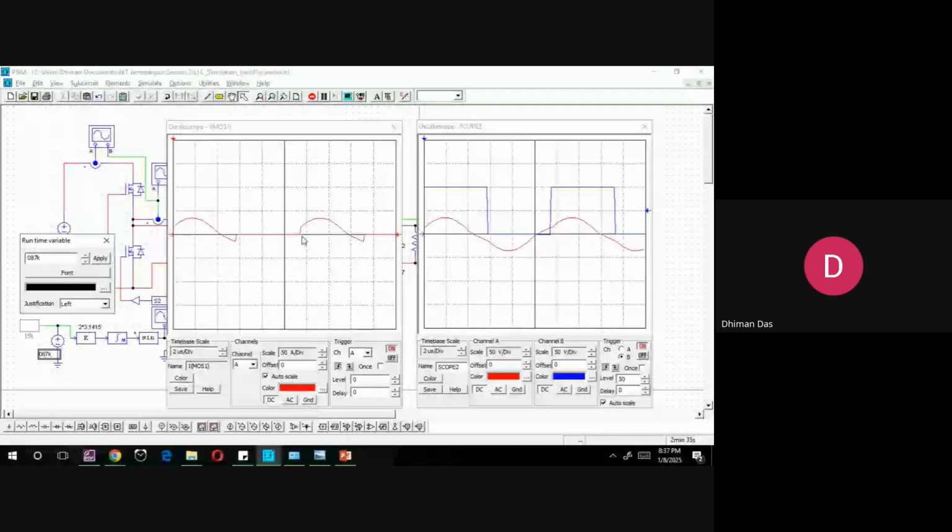That means here it happens ZCS and it goes into the capacitive region of the gain curve. So here this is ZCS, negative current at turn off, but I need negative current at turn on. So when you operate at this condition, your switch will definitely blow, because this zero current cannot do anything with the voltage, because your switch is very sensitive to voltage.